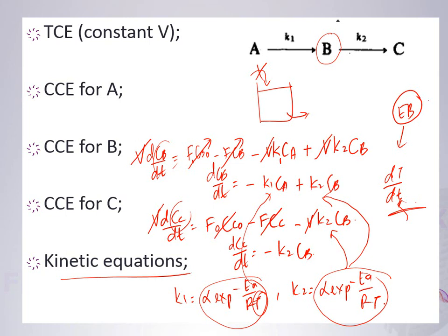But however you cool it, because the cooling is circulating around the vessel, you cannot just put ice inside, you see. So it will still take time, and once the temperature goes down, it will still affect your CA, CB and CC, the profile of your graph too. That's why you must have correct timing, what to do, what the temperature is, the energy balance of the jacket, and the energy balance of the process fluid.